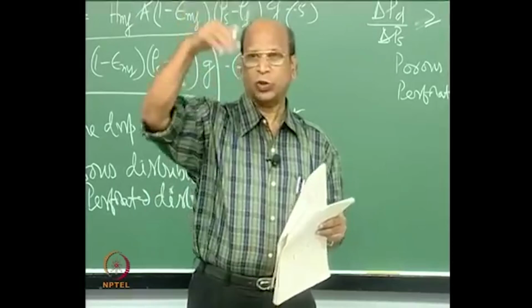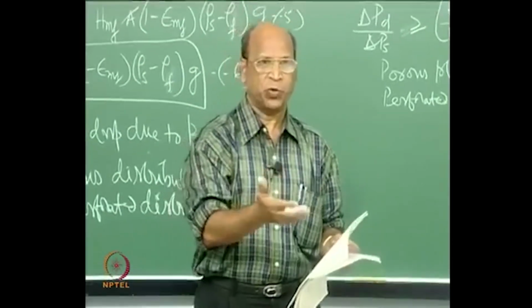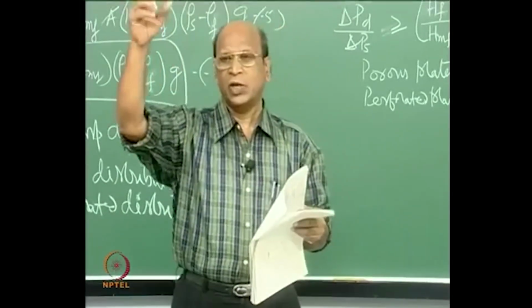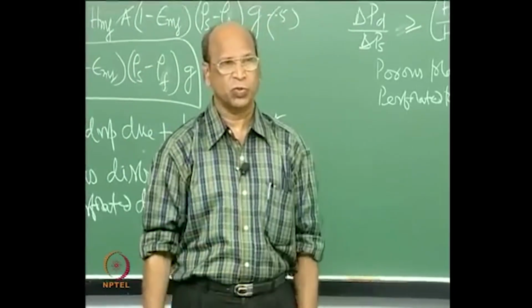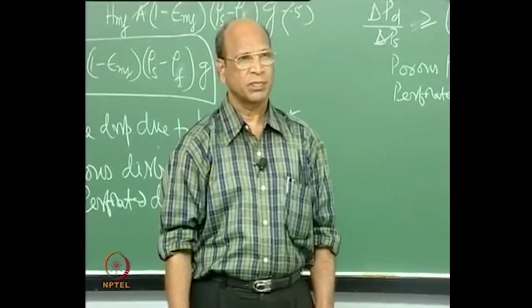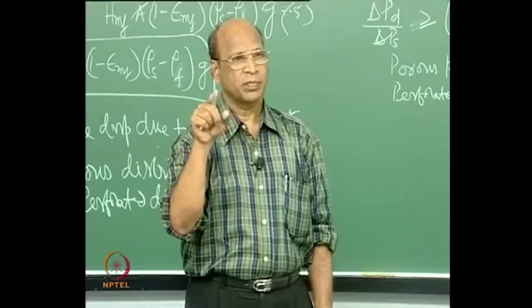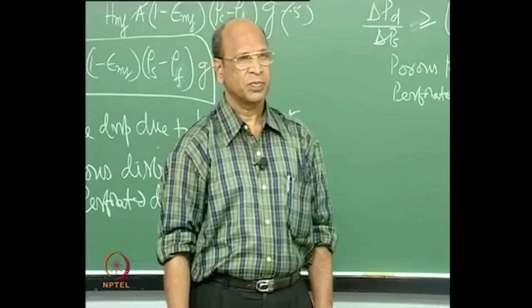Then it has fluidized to certain level, where of course packed bed also you can take as mf, minimum fluidization velocity, right, epsilon mf, and at some other high velocities you have Hf and epsilon f. What should be the relation between these two? What will happen to 1 minus epsilon f?